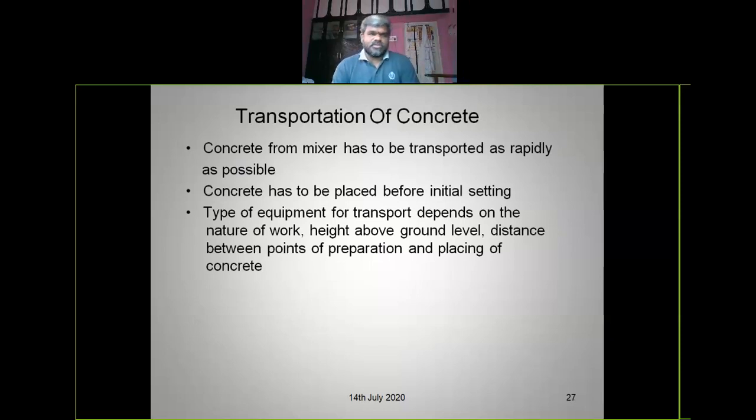Mixing and transportation. Concrete from the mixer has to be transported as rapidly as possible. Why? Because within 1 hour or 2 hours it should be placed. The concrete has to be placed before initial setting time, right? So 30 minutes is the initial time.